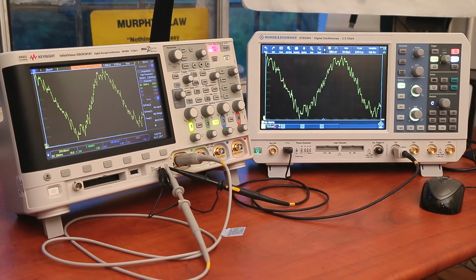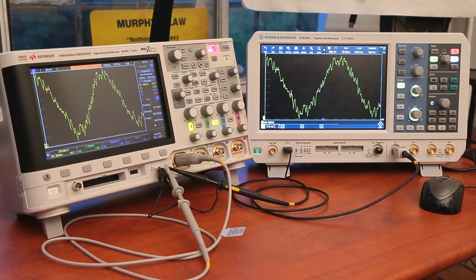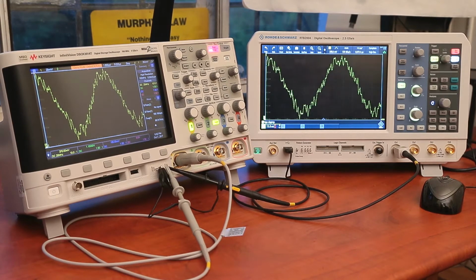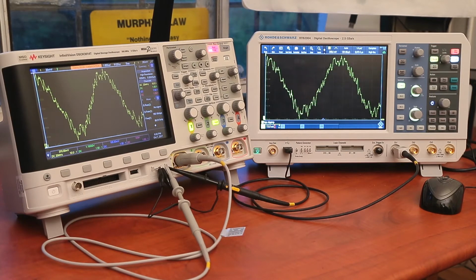These screens were produced using high resolution mode on both scopes, and I think 5 megasamples for the memory depth on the RTB2004. Obviously the memory depth on the Keysight is not adjustable, the scope just uses the maximum amount which it can do. But interestingly enough, and I'm going to zoom in in a moment so you can see them clearly on the screen, the actual detail, because of the 10-bit resolution ADC on the RTB2004 as opposed to the 8-bit, which is what the Keysight has and most scopes have,